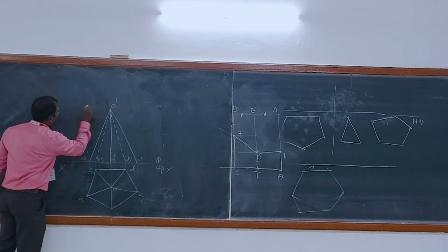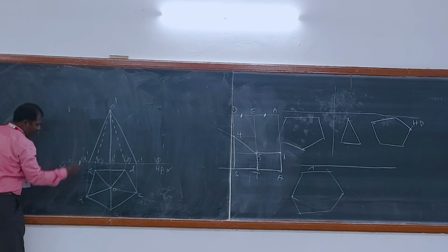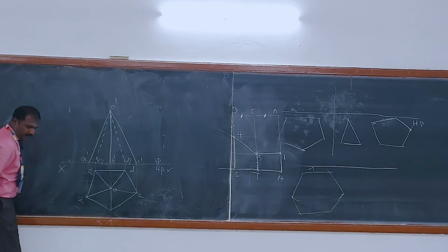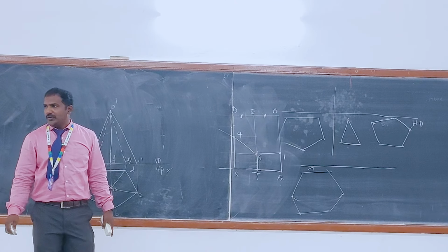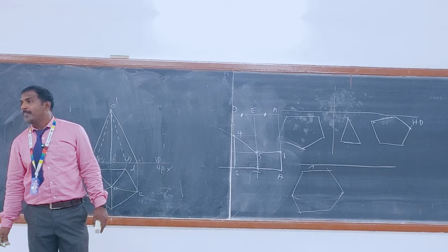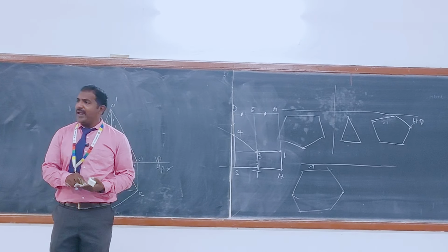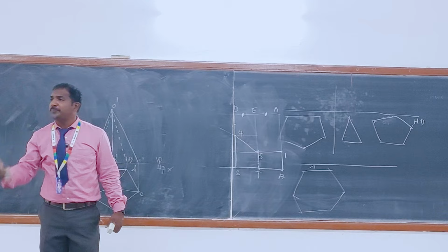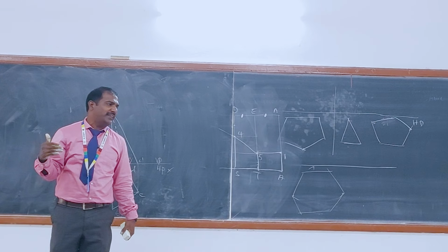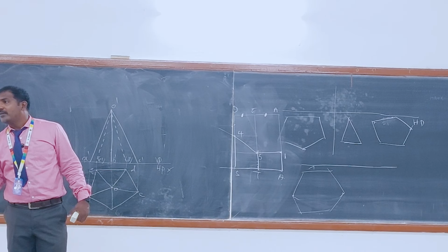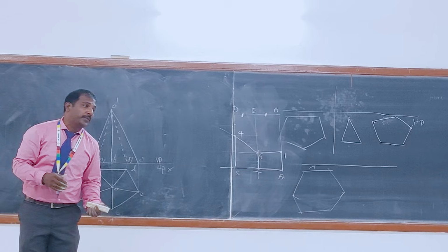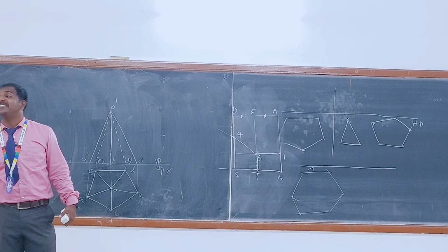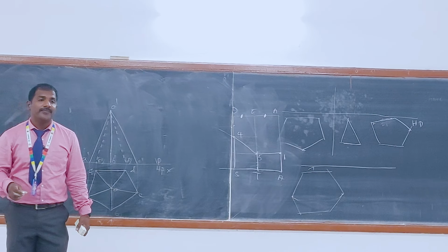Give the dimensions for any edge, one of its edges. That's it. Got it? It is cut by a cutting plane. Perpendicular to where? Will you draw on VP or HP? VP. Perpendicular to VP, then inclined at 55 degrees to HP. Then where does it meet the axis? At what distance? 20 mm from the apex.